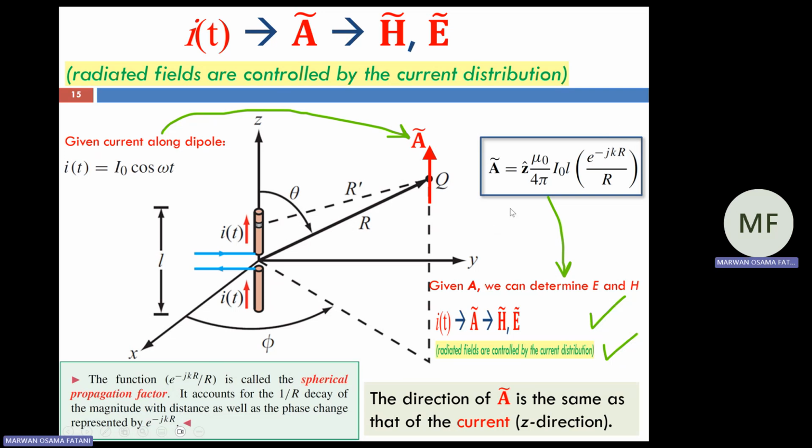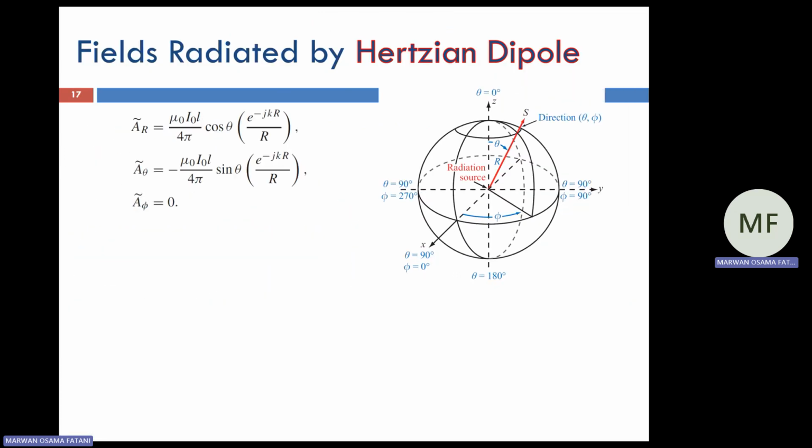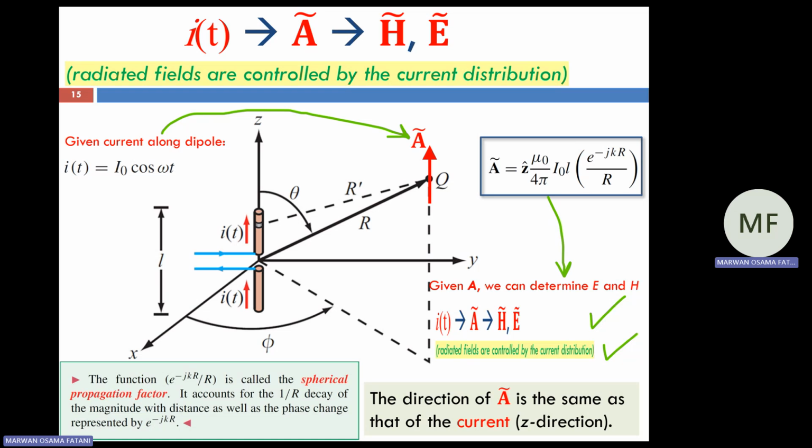So we can think that our electric field is proportional to the current and the length of the wire and inversely proportional to the radius and the wavelength. And this is exactly the same as with the magnetic field. They are both proportional to the current and the length of the antenna, or half-wave dipole antenna, and inversely proportional to the radius and lambda.